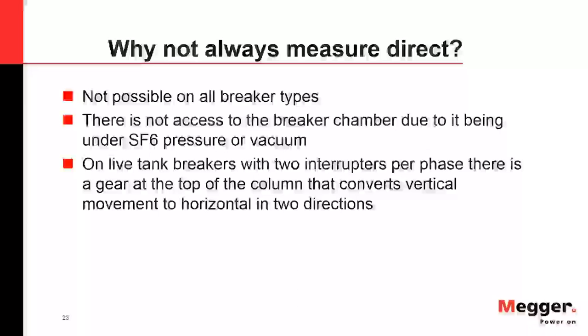So DRM stands for dynamic resistance measurement. The way I look at this is you're basically getting a micro-ohm measurement while you're operating the circuit breaker. So you use a time and travel device, an analyzer, you hook up your transducer and all that. But in conjunction with that, you use a separate little attachment to your analyzer where you're injecting current while you're operating the circuit breaker.